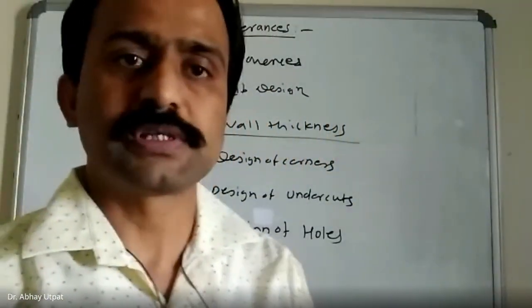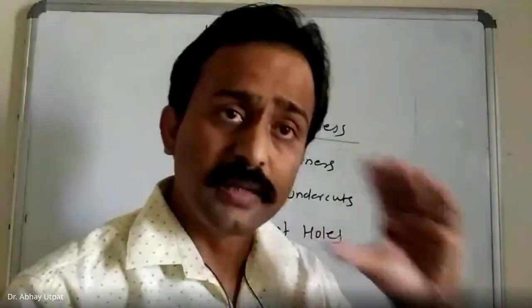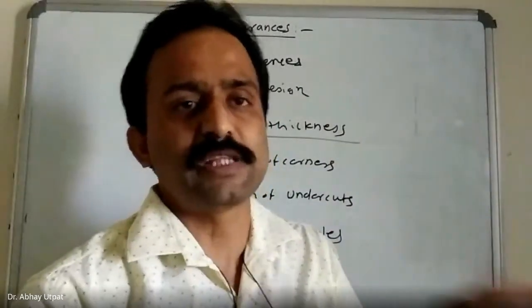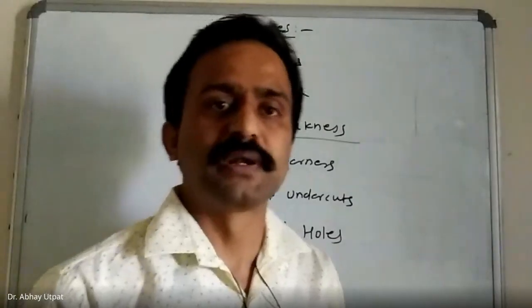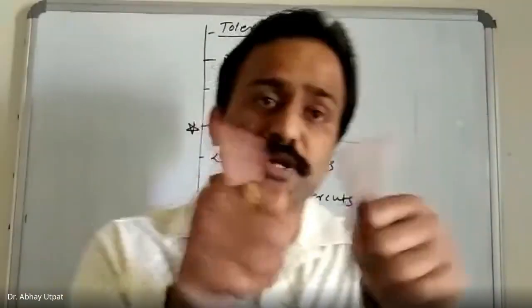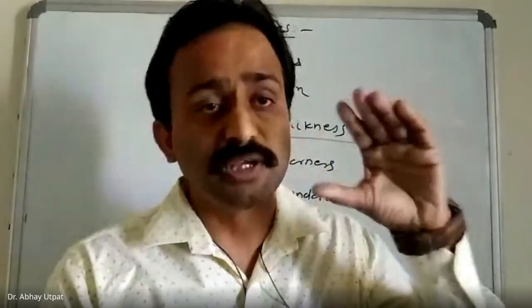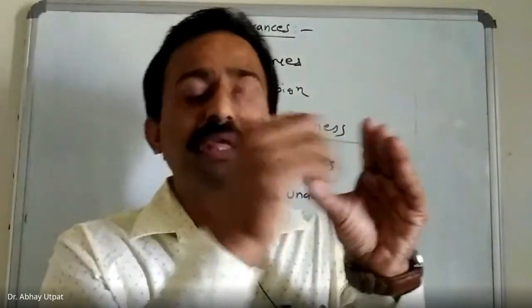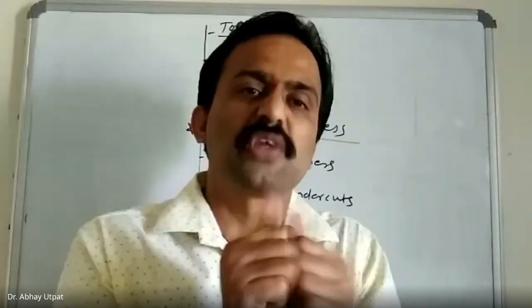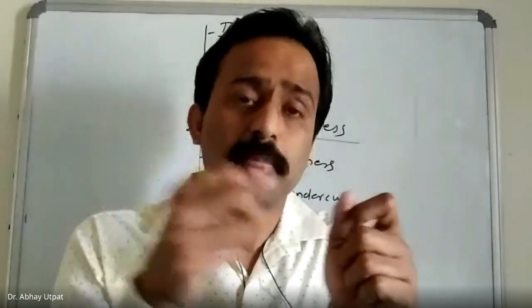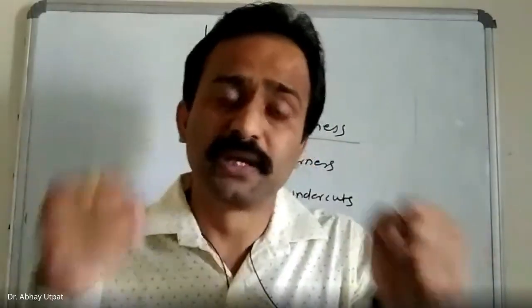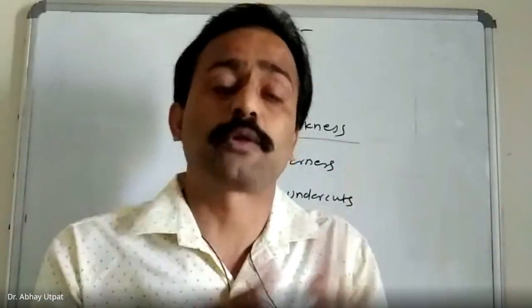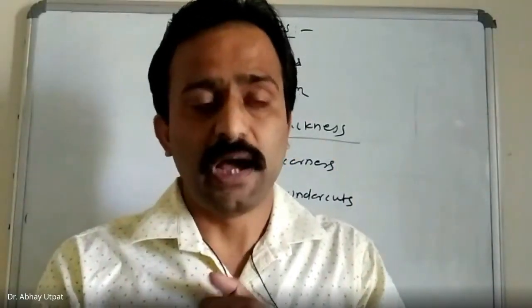Unmute yourself now, Ajinkya. So thick metallic part may solidify faster than thick plastic part because it is a simple heat transfer concept. It is a good conductor of heat. Metallic parts are good conductors of heat. Plastic parts are not good conductors of heat. That's why if the thickness of the plastic part is more, from the outer side you may feel that it is solidified, but the inner core part will not solidify fast, and there is a difficulty in extraction of heat from the outer wall of the plastic for the inner temperature of the core part of the plastic. I hope you are getting my point.